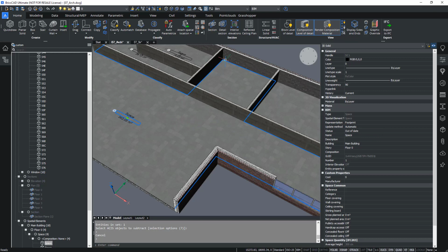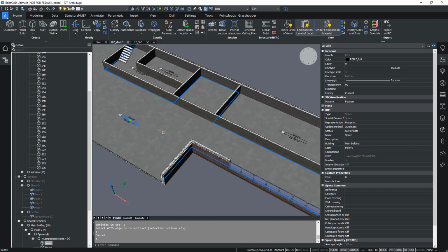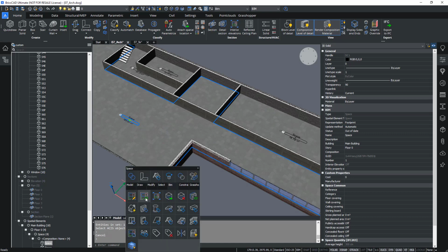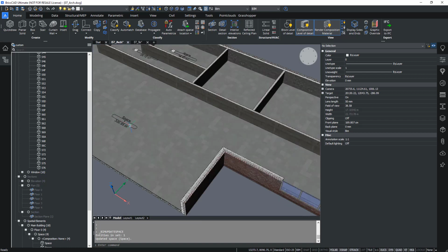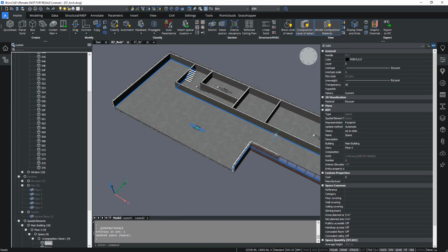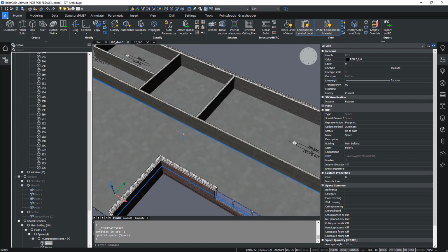However, if we select it, it still has this protrusion. So we will adapt it to the new space by calling the BIM update space command from the BIM tab in the pod. And then you will see that the space adapts, it's no longer out of date, and here the footprint representation is now nicely until this line.